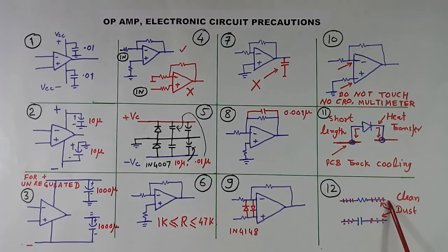To remove that gum, you must clean both sides of the resistor, capacitor, diode, whatever component, even an IC with leads, not chip type. Chip type has no lead, just a very small terminal. Wherever possible, you should clean these leads using a knife.